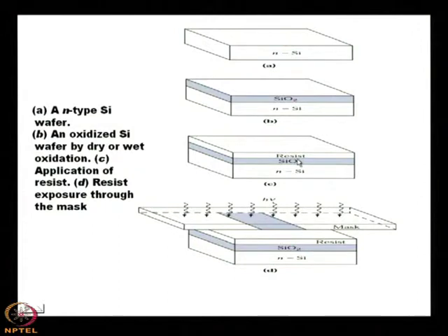Then the next step is to use a photoresist. You see that here we have written that photoresist must be coated on the SiO2 surface. So, first you take the substrate, you make the oxidation on the surface, and above the oxide surface you coat it using some photoresist.